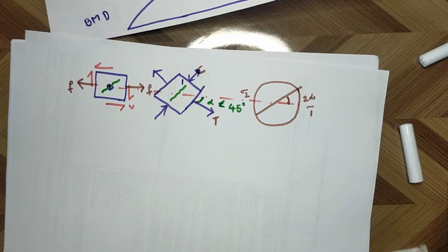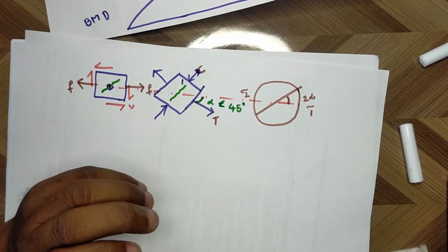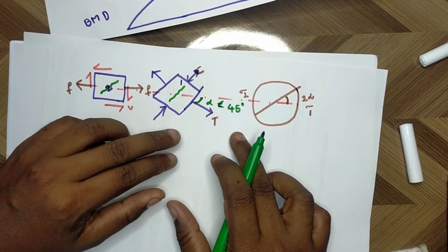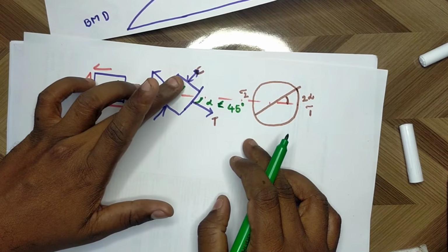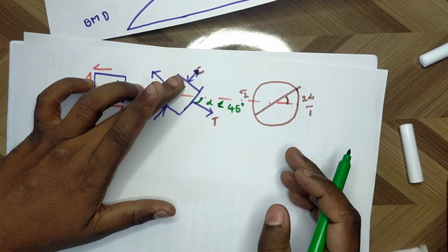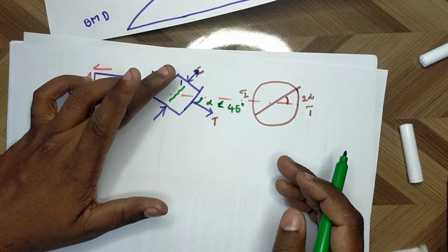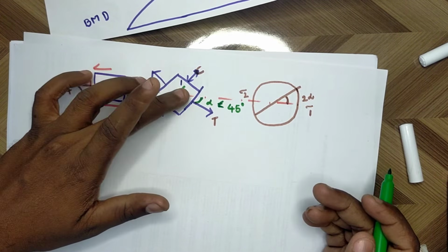As the moment is maximum at midspan, cracks due to flexure occur nearly at midspan. The cracks are formed at the bottom edge and perpendicular to sigma 1. Since sigma 1 is parallel to the edge, the cracks are perpendicular to the edge. Okay.